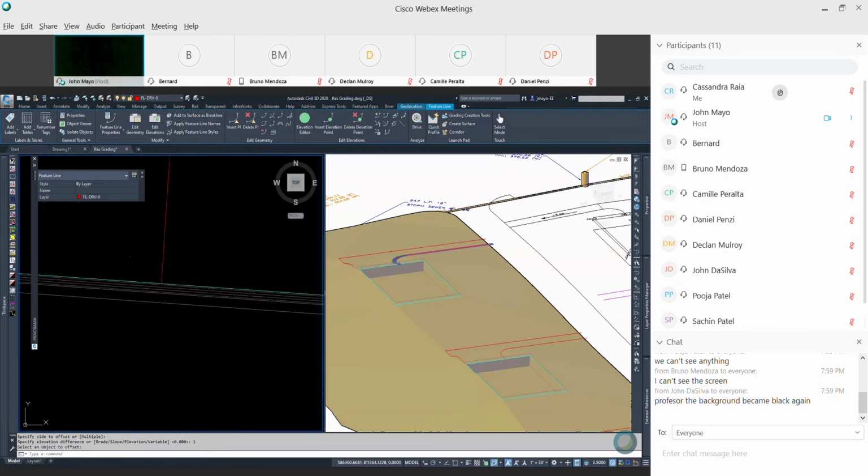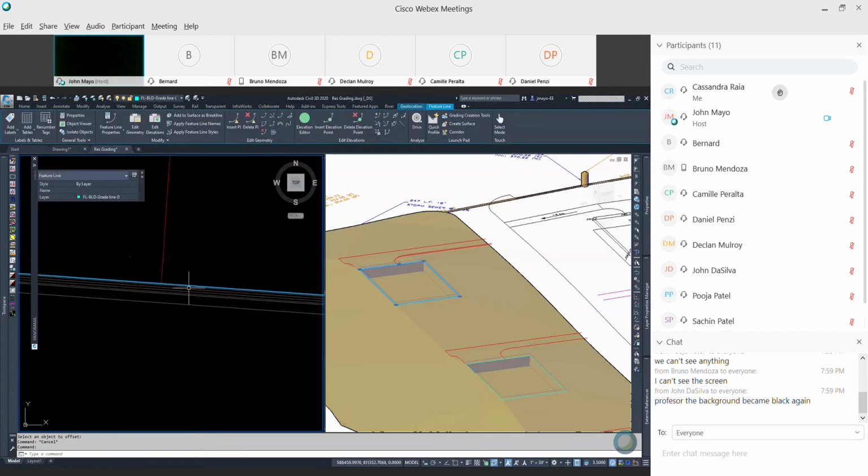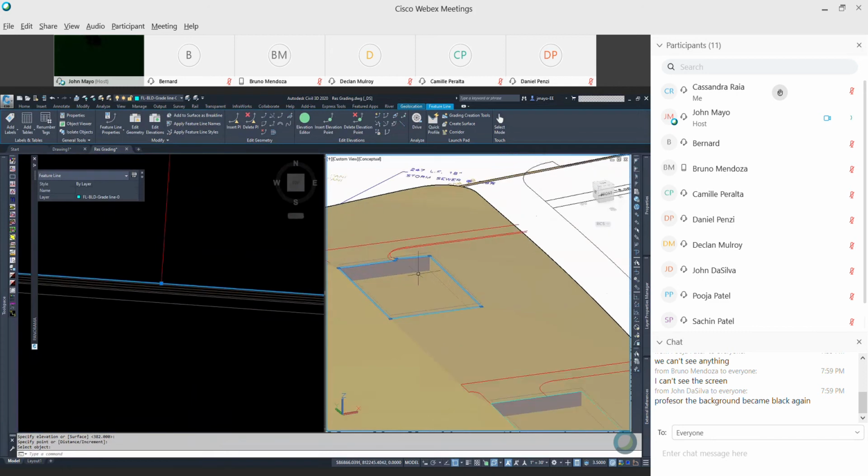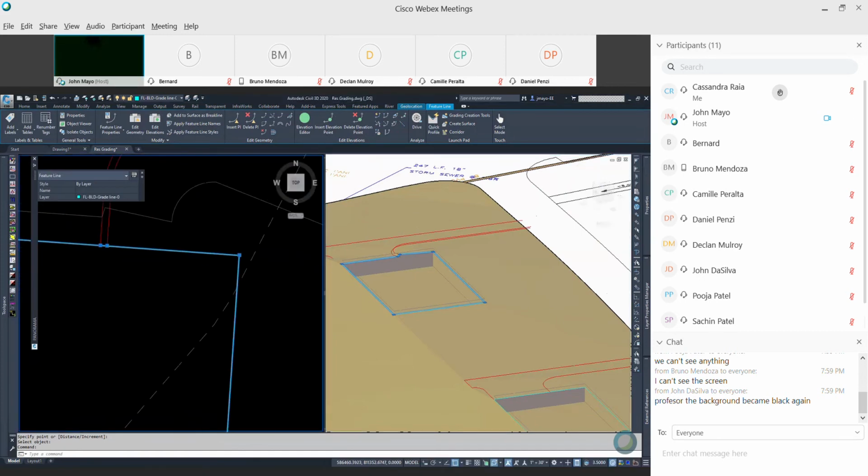Now, what did I do here? I made an intersection of 2 feature lines. And at every intersection, I want a PI if I want to be able to control that elevation from either object. All right, so we note in 3D view that my grades are changing a little bit here around the grade line. And that's all right, I want it to change a little bit.